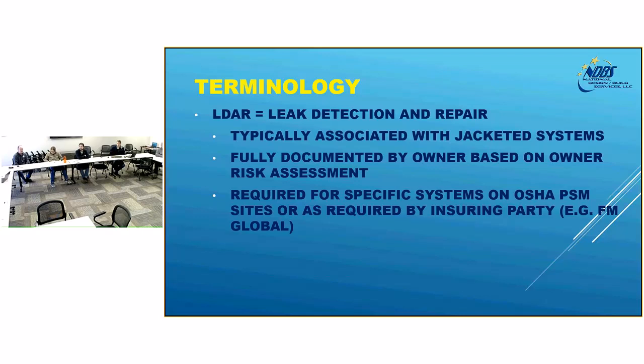A couple more terms just to throw at you guys. You may run into these at some point. LDAR systems are typically a jacketed system where an owner is conveying a category M fluid that's highly hazardous or toxic to human health, and therefore they have to make visual inspections on a routine basis and or put other means to detect leaks or breaks in not only the piping system but every joint and every valve.